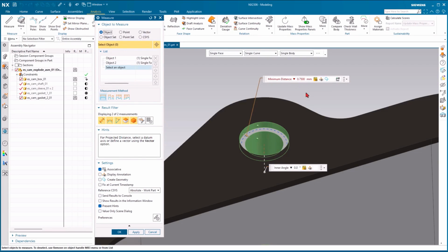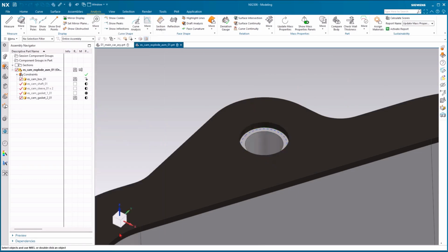Because we told the software to flag this validation or requirement as an error if it's outside of the requirements specified, it's going to flag that as an error. That color is going to be shown in red. So right away we're getting feedback on this dimension. We can see the lettering has gone from a black font to a red font, but that's okay. We'll just go ahead and finish the operation here. I'll select OK and complete creating the requirement there.